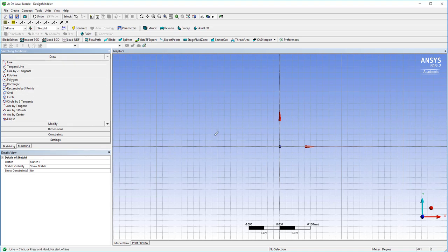the horizontal x-axis. So begin by creating the inlet of the nozzle, and let's say it's 3 centimeters in radius, and then you see this H here that comes up means that this line is truly horizontal. But we don't want it to be horizontal. Let's have a converging section 3 centimeters wide, and then let's create a diverging section of equal length.